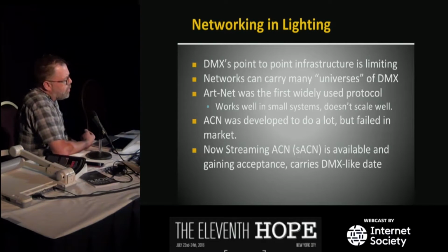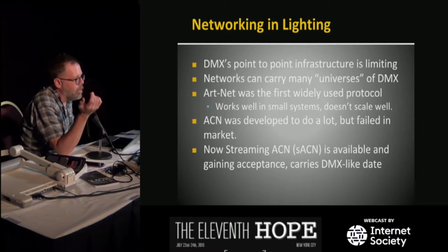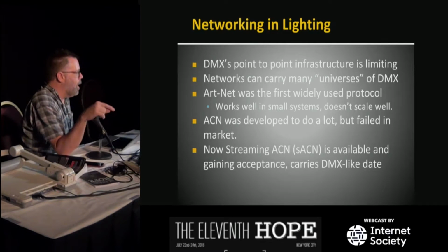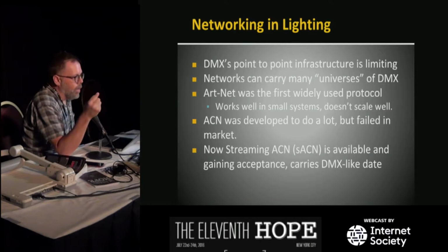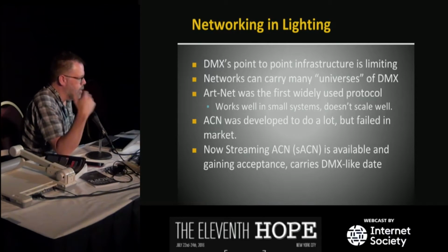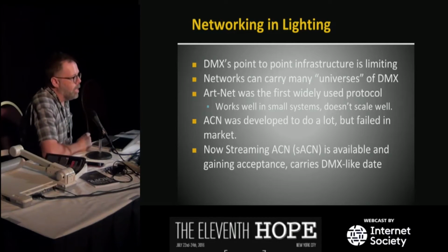These are used in a lot of cases. In here with a few lights, maybe you don't need it, but if you're doing a big concert, where with the old DMX stuff you would have had 50 cables from your console up to the lighting truss, that's a pain to put in and out every day and to deal with. So now we can run one network cable and carry all that same data up there. Practical reasons like that are really what started the adoption.